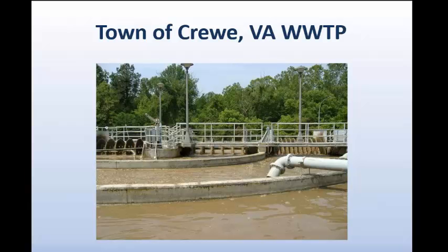So our challenge with the existing structure and equipment was to create that opposite environment, the environment that's very low to ideally 0 in free dissolved oxygen. And we needed to do that in at least one channel while we still maintained that high oxygen level in at least one channel. So the first attempts were, as you look at that picture, you'll see there are discs on the shaft. And we tried to remove some of the discs, which was the prescribed way to alter the dissolved oxygen content in a respective channel.